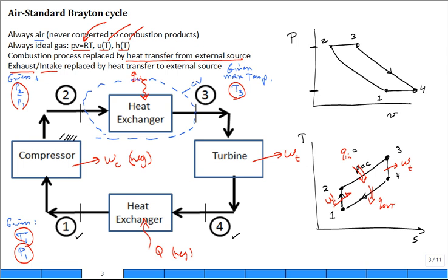Okay. I know that you can start with the most general form of the first law. The rate of change of energy in the control volume with respect to time equals the rate at which it's flowing in with the heat minus the rate at which it flows out across the boundary of the control volume with shaft power, plus the mass flow rate, and it brings in enthalpy.